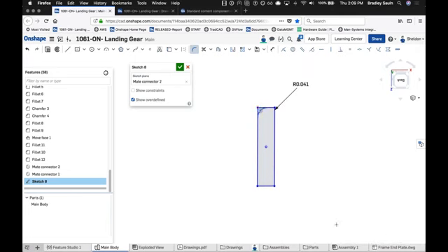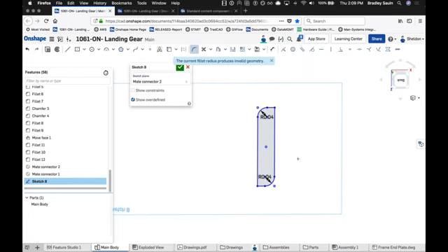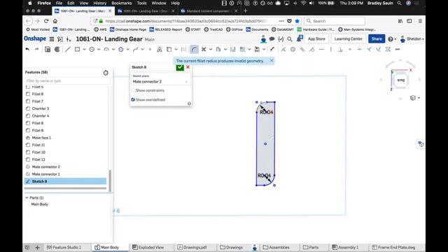And then I can left click to accept it, or I could have always just double clicked on the radius value, started typing it in, or after I do the left click, I can type in a more appropriate value. So let's do a clean 0.04 inches. Excellent. And then I can use that same radius to apply across the board. And we should be good to go, at least on these two corners as we saw.